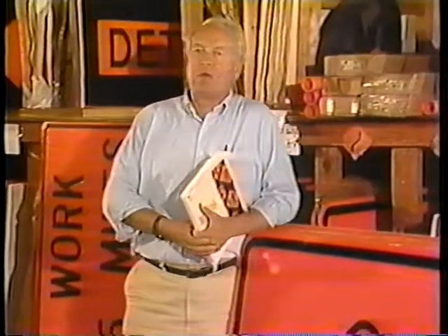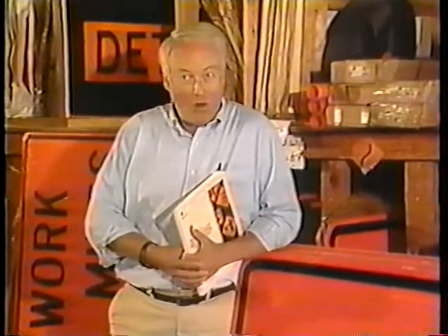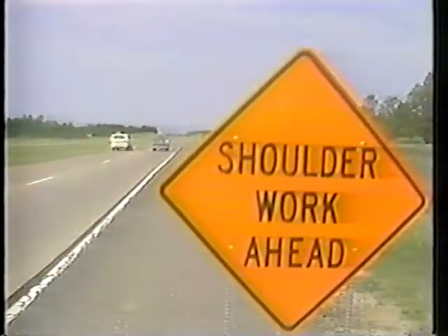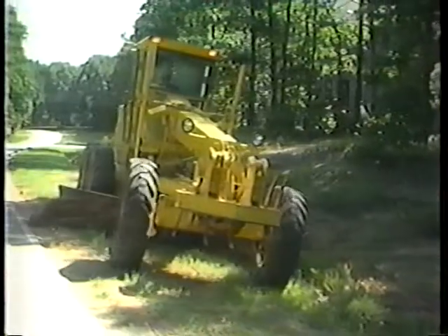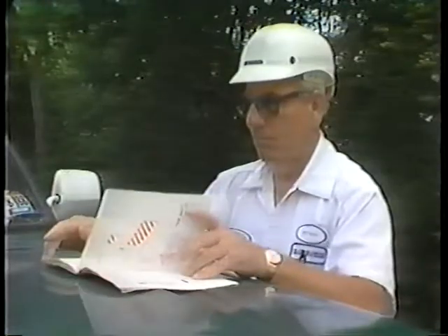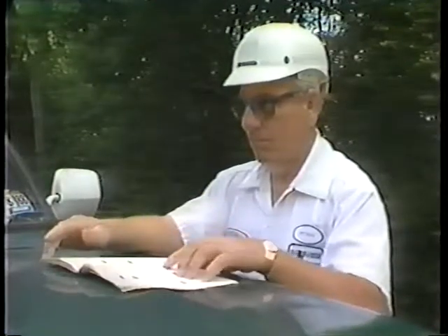All signs should be made in a professional sign shop or purchased from a reputable business. Homemade signs are immediately suspect and do not command driver respect. Now, when choosing signs, the following should be considered. Choose signs that are appropriate, that accurately describe the work situation. Use your common sense and the Manual on Uniform Traffic Control Devices in selecting signs.